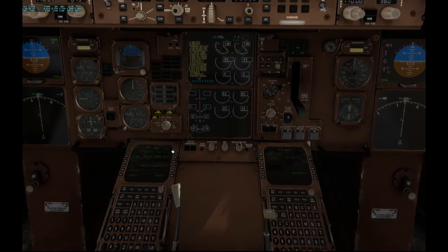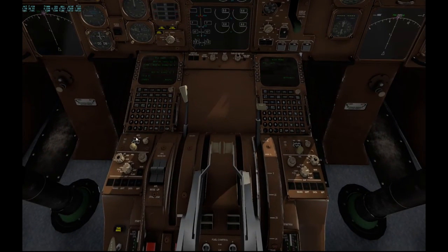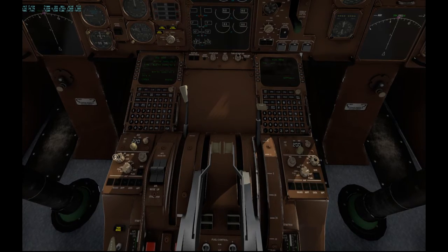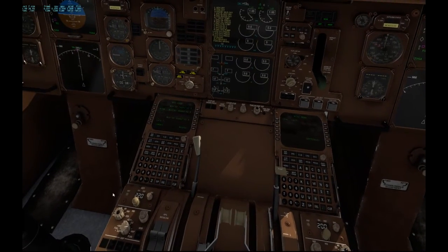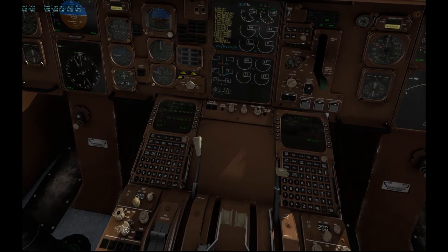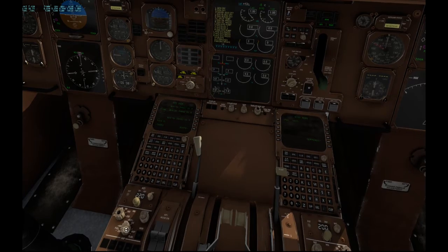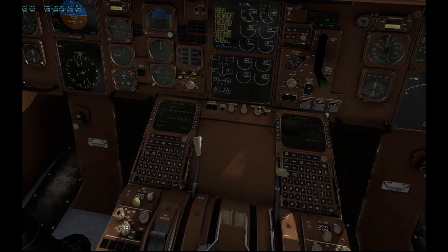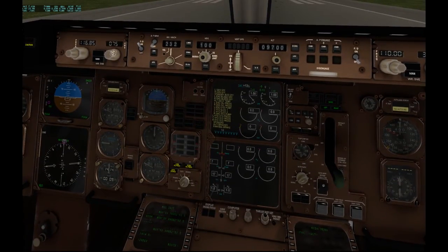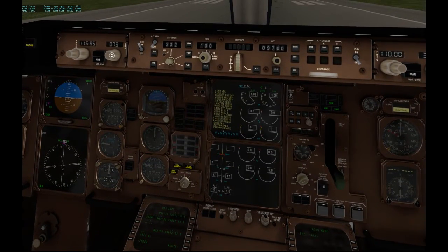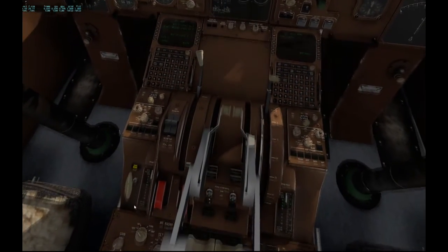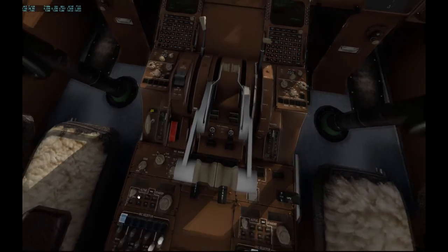And moving down. The EFIS, here you can do your decision height. Right here. And here you can change what shows up here. Alright, so let's go ahead and do ILS, which I want to say uses the VOR or NAV1. I'm sorry, NAV2. See, this doesn't change it. But if you come to here, you'd have to zoom out.